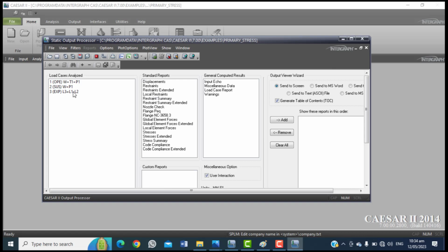So as you can see, the primary problem we had has been resolved. The first time, we had a hoop stress problem, which was just due to pressure and insufficient thickness. The pressure to thickness ratio was very, very high, so we needed to reduce it by increasing our minimum thickness.